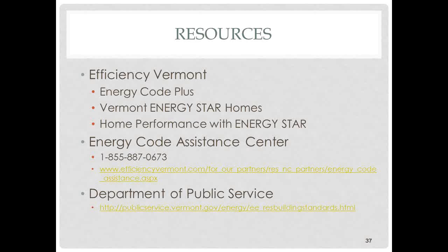The other thing is that all these folks have blower doors. They could do a blower door test for you if you want to use that compliance method. Also, they've all been trained to do this worst case depressurization test, so they could do that for you too.